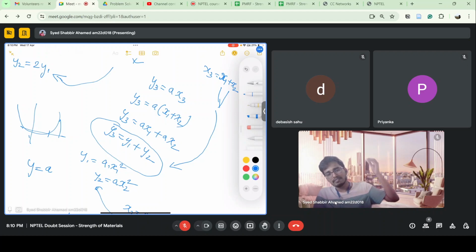So we have seen that ductile materials don't fail by tension. Ductile materials mainly fail by shear. So that's why we go for maximum principal stress theory, maximum shear stress theory, and also distortion energy theory, which is also called von Mises stress theory, or octahedral stress theory. It is an advancement of the Tresca yield, maximum principal stress, and maximum shear stress theories. Ductile materials fail differently compared to brittle materials.